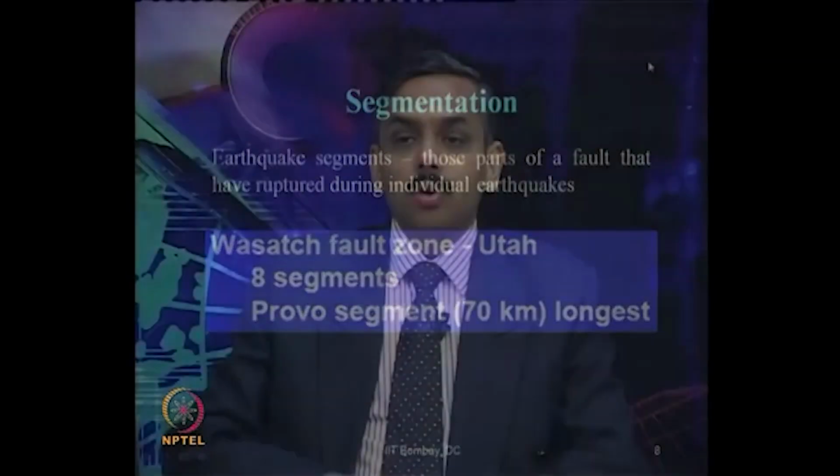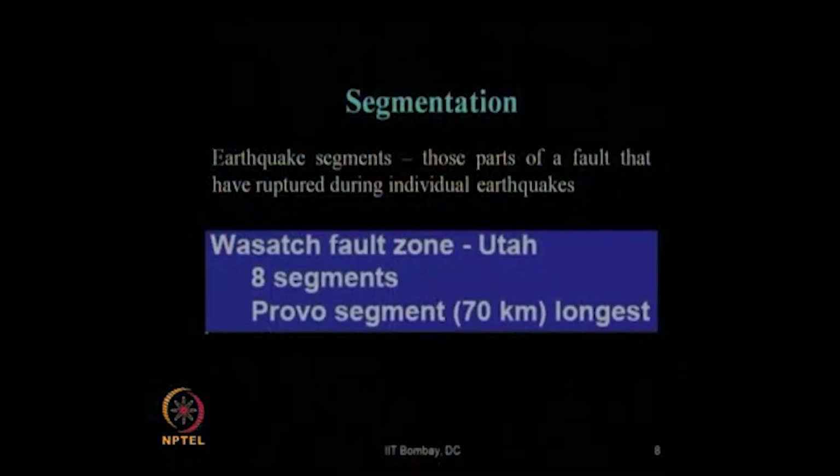Now, let us come to the next important part of this hazard analysis, which is known as segmentation. First are the magnitude indicators, that is, first we have to find out the magnitude of the earthquake, which we have done using either the fault characteristics, if it is a fault based earthquake, or through the plate tectonic movement, if it is a plate tectonic based earthquake, right. Now, we have to segment the earthquake, that is earthquake segmentation. Let us see how we do this earthquake segmentation.